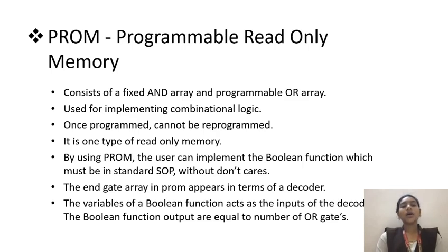This is used in implementing combinational logic circuits, and if it is programmed once, it cannot be reprogrammed. While creating the PROM, we have to take measures so that it is not reprogrammed again, and it is one type of read-only memory.